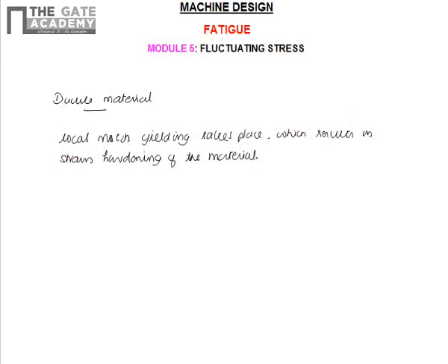So while dealing with static loads, we have seen that for ductile materials, the stress concentration factor need not be considered, because even if the concentration of stresses takes place, the material yields locally and strain hardens. So this does not affect the functional properties of the material. But in the case of brittle materials, there is no strain hardening or yielding taking place. Therefore, the stress concentration factor has to be taken care of for brittle materials.